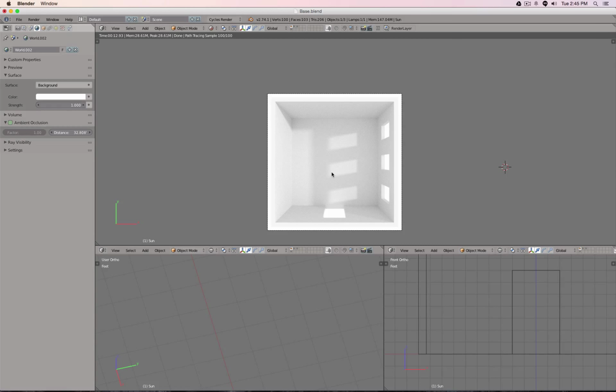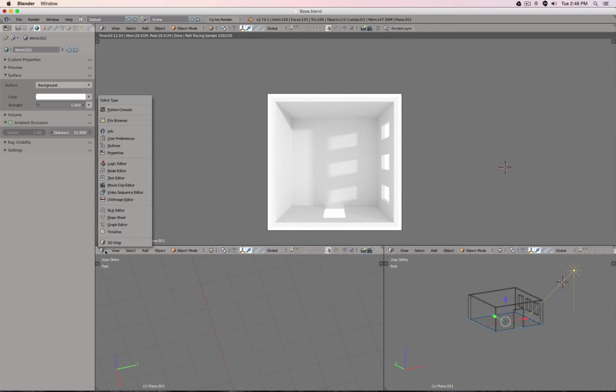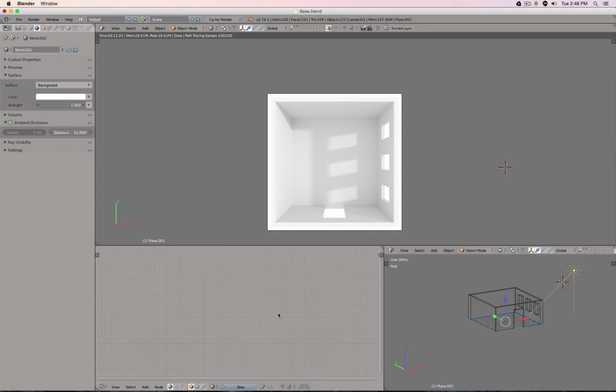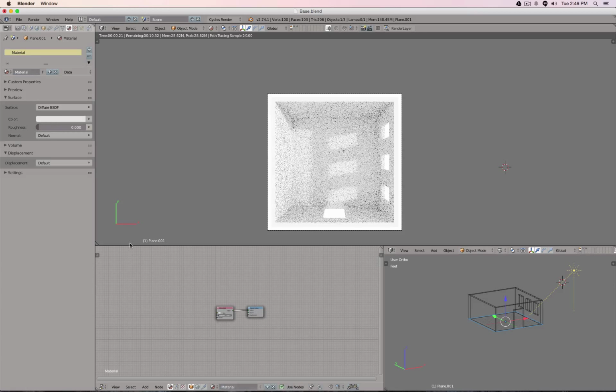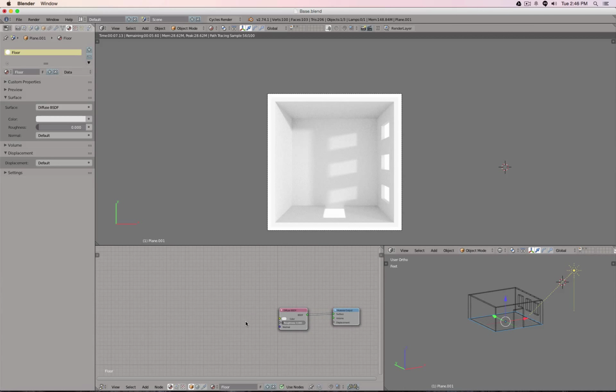So let's add a little bit of material to the floor. Let's make a repeat on how to create materials. So I click my ground plane. See, it's selected, and then here this one I can set to the node editor. Go to materials, click new. I can do the same here, exactly the same button. Maybe call this one floor. Okay, perfect.